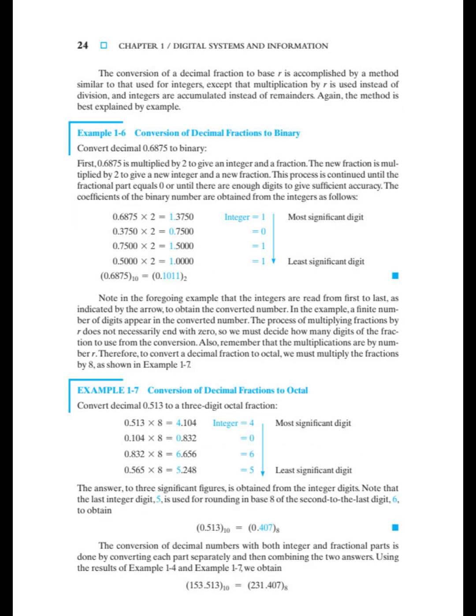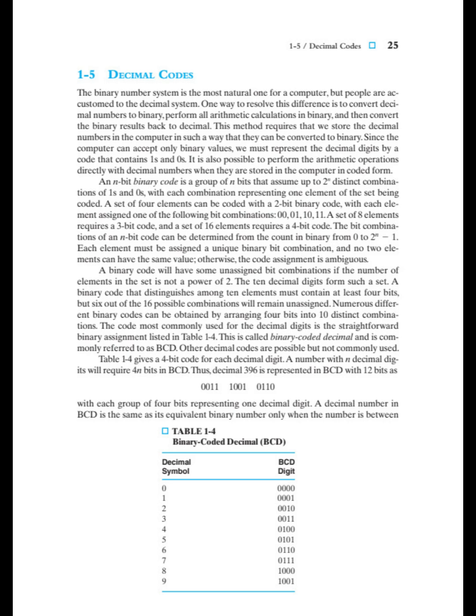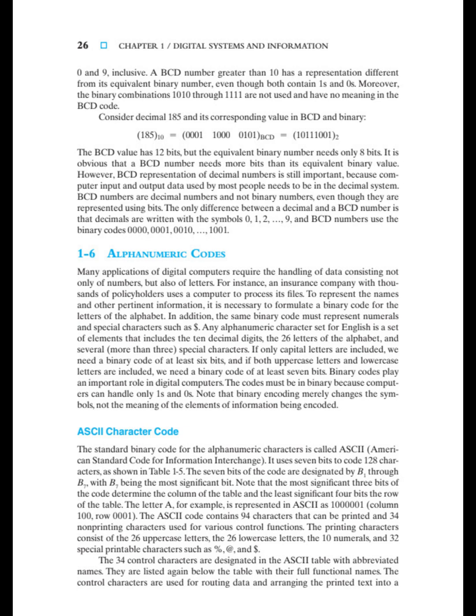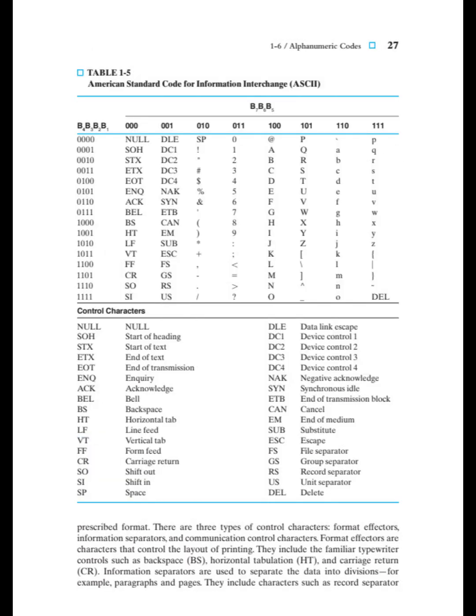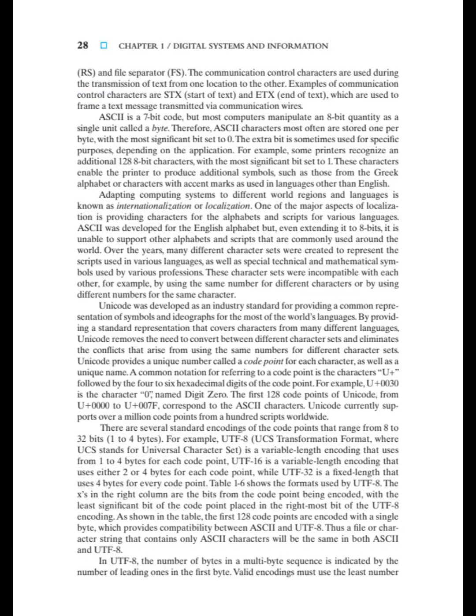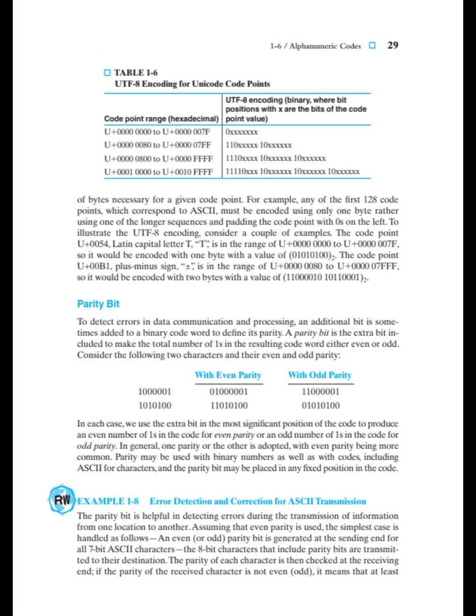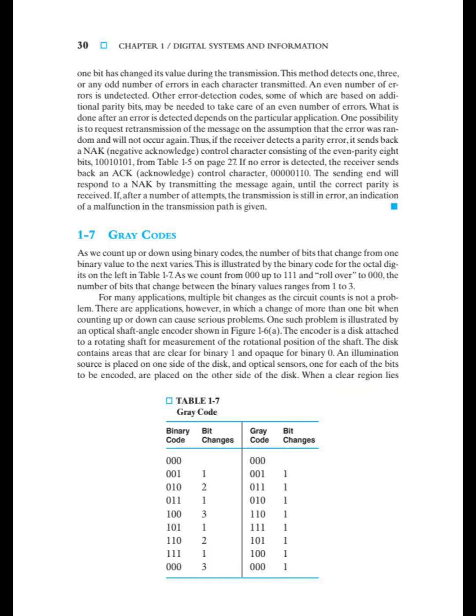It is. Now, with digital systems, there's a limit to how big a number you can represent, right? Absolutely. It depends on how many bits the hardware uses. For an 8-bit unsigned integer, you have 8 binary digits. That means you can represent 2 to the 8th power, which is 256 different values. So from 0 to 255. Right. More bits, wider range. A 32-bit integer can represent values up to over 4 billion. So the number of bits is really important.